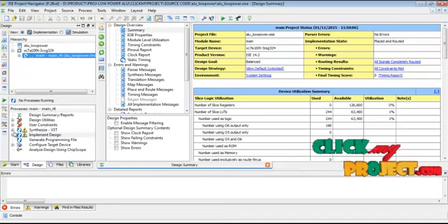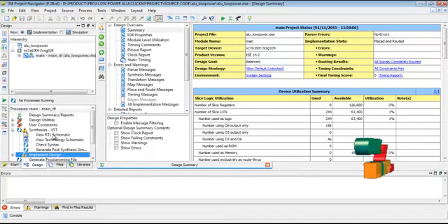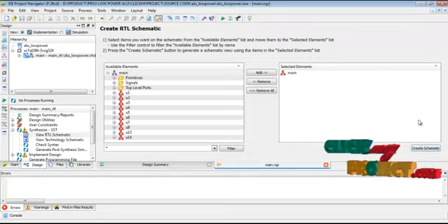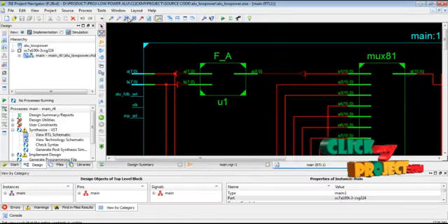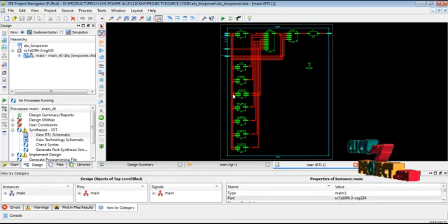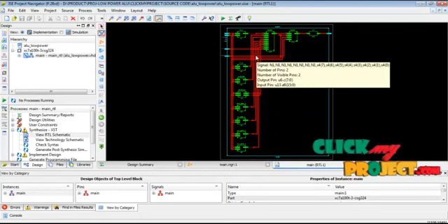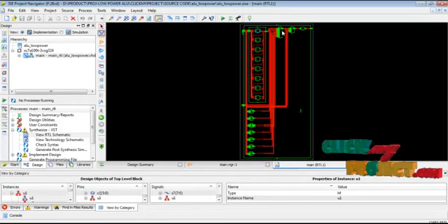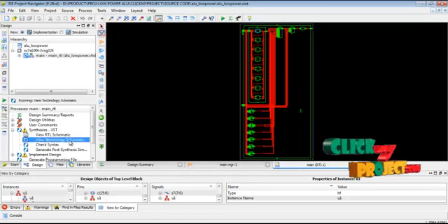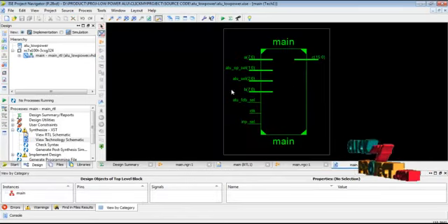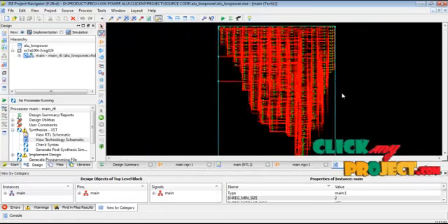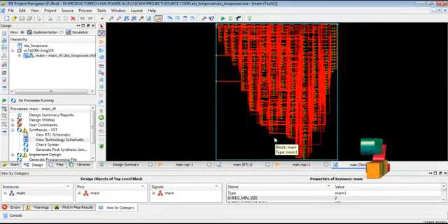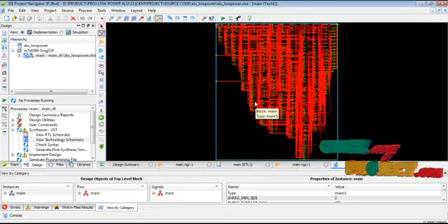The implementation process is mainly used to produce the synthesis report and to create the RTL schematic diagram, then add and create the schematic. Then the ALU process is applied to the RTL diagrammatic representation, showing the logical blocks placed in our architecture. Then we create the technology diagram, add and create the schematic, and open the technology RTL representation. This technology diagram is mainly used to show the lookup tables, wire length and flip-flop pairs applied to our ALU architecture process.